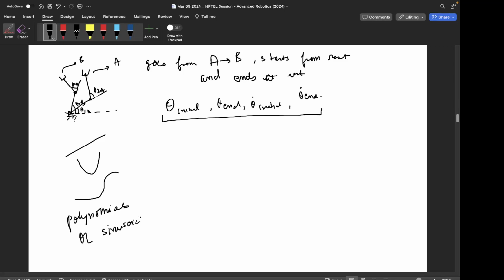What do we look at when making the choice? A very obvious thing is what velocities and rates we get. We don't want a trajectory which has a lot of sharp changes, or a jerky trajectory. We would want the trajectory to be smooth, changing values gradually, not rapidly. For most practical purposes, sometimes it might be necessary to be abrupt, but generally I'm speaking.